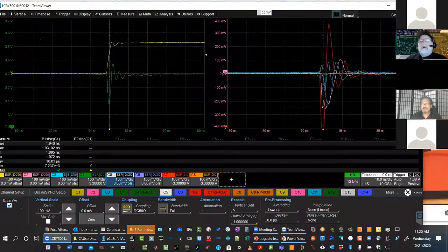Now, while we're doing that, look at the number. This scale is 100 millivolts per division. We've got a 200 millivolt drop out of 3 volts. So there's our roughly 6, 7, 8% voltage drop, switching noise just when these IO are switching. This is what's going on die.